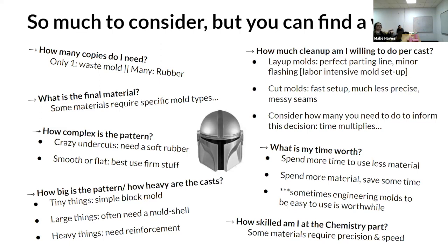It's great for certain things, and if you have a real specific need, you can make a mold that can get you any outcome you like. It's just a question of how much investment it is. The time versus money investment is always going to be the thing. But I would just say don't skimp on materials to save a little bit of money. That is the number one reason that molds fail.